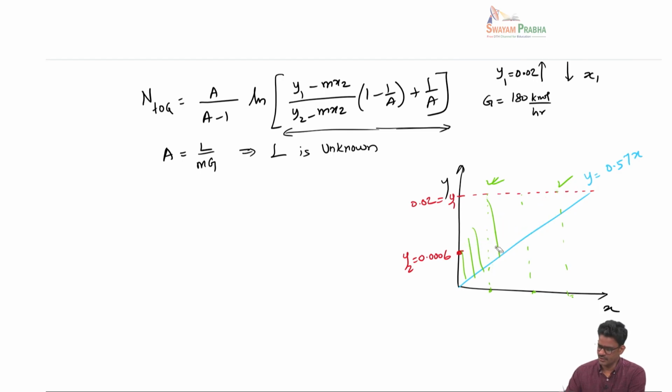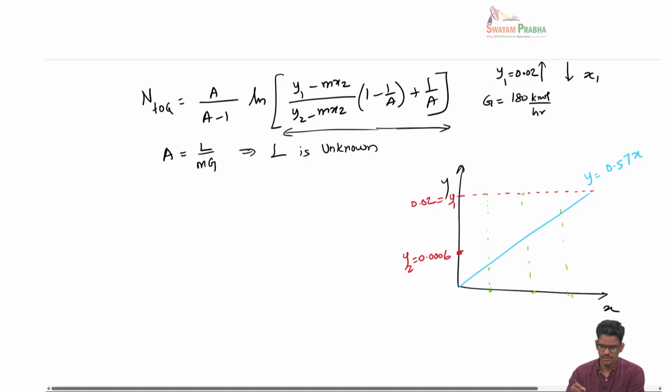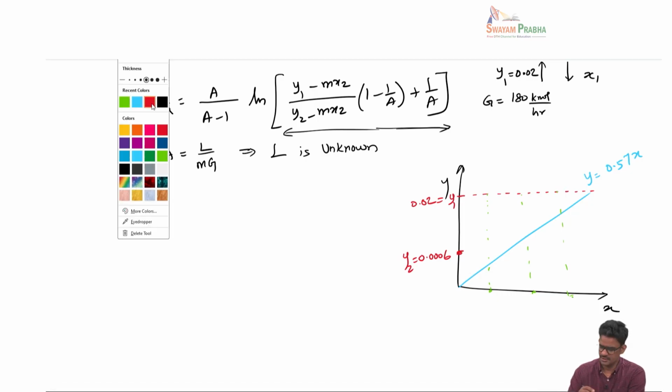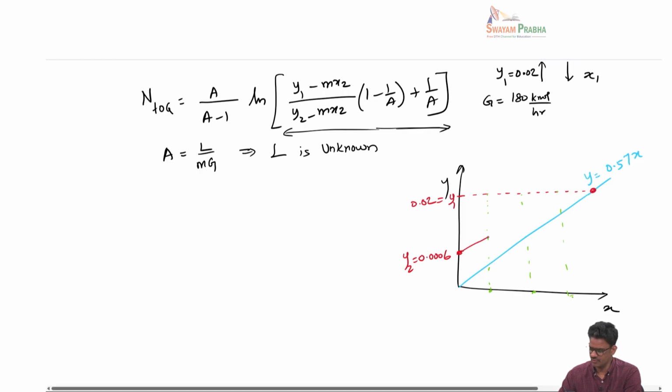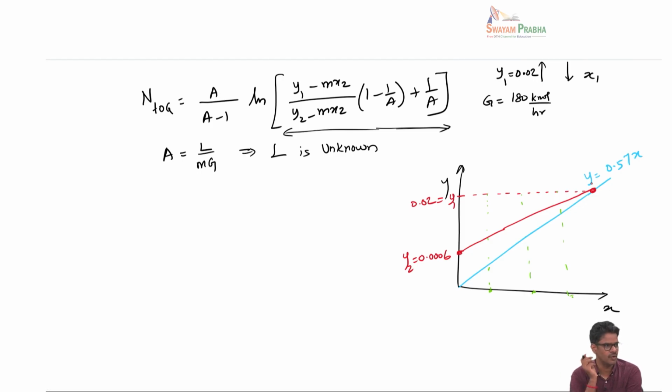So I'll just delete all this. So minimum would be something like, the minimum is one where the outgoing liquid is in equilibrium with the incoming gas. And we can calculate this. I know all the information. So this would be the slope corresponding to LS minimum.